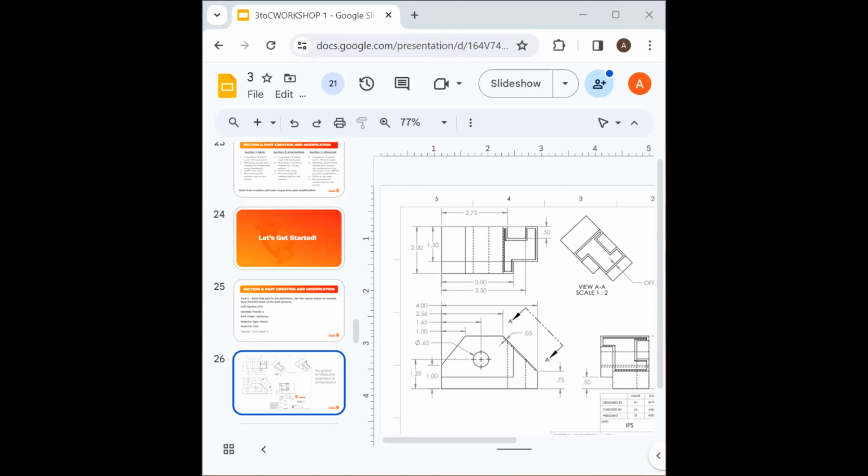When you're dimensioning, your main goal is going to be to have everything be a black line, because that means it's fully defined, and that should always be your goal when you're defining, because it's just good practice. So I'm going to look at my example here, and I'm going to notice first my critical dimensions. I know this is going to be 4 inches long.